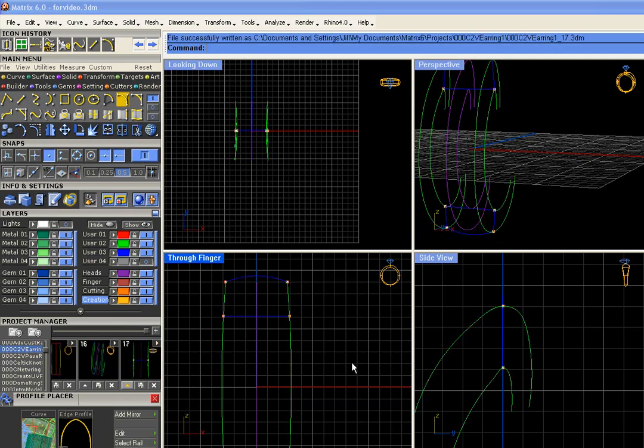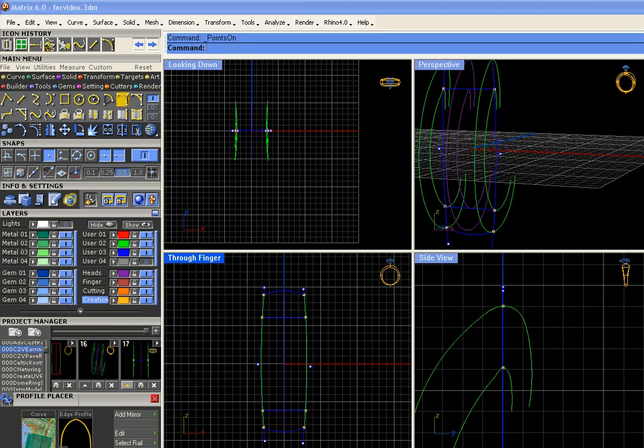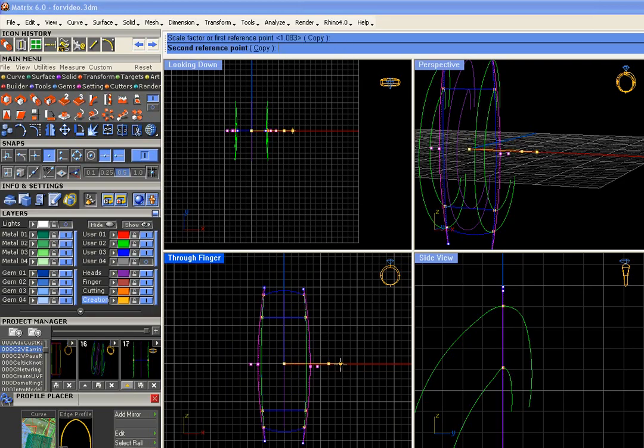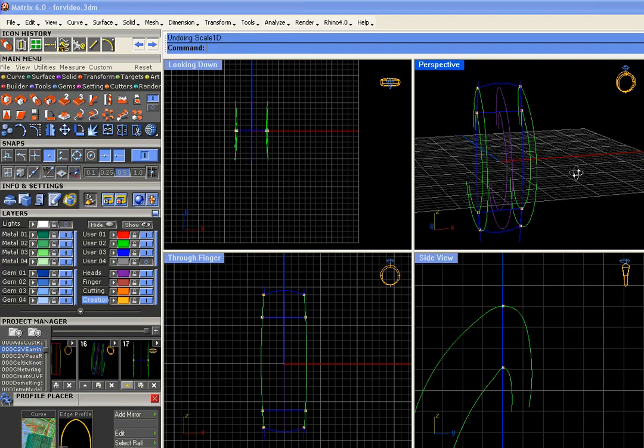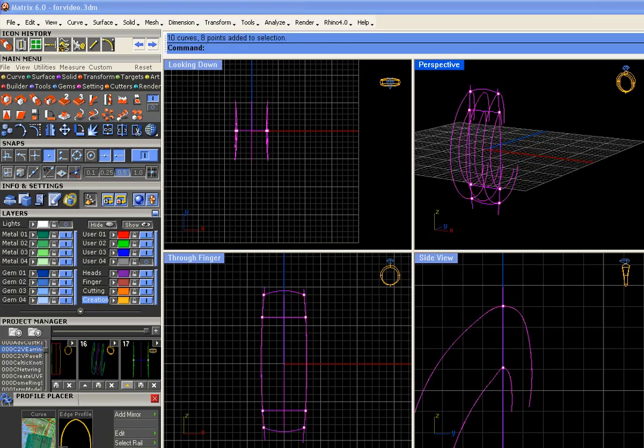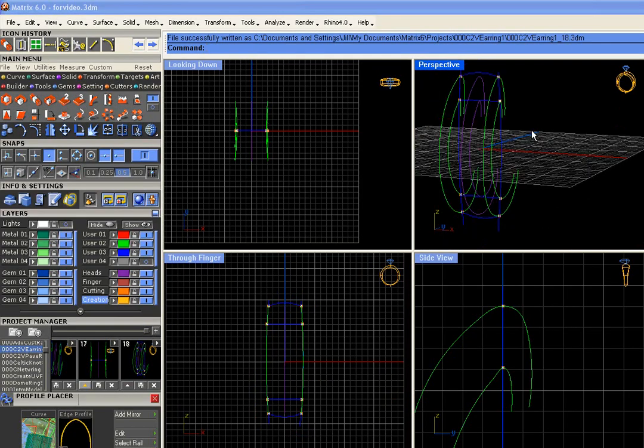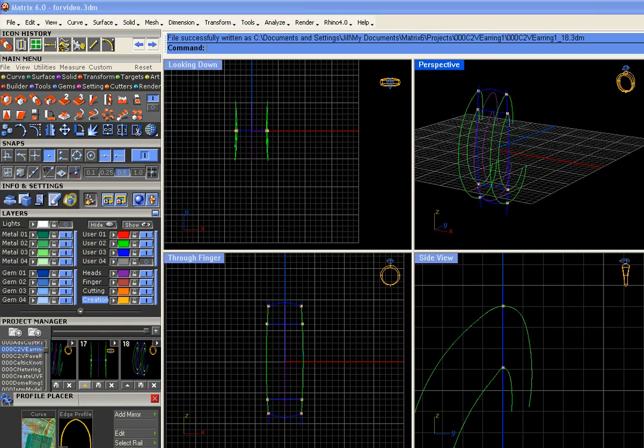And if you want to check and see, just bring back your original curves that you had hid, turn on their control points, grab them, and using, say, transform, we can push the center two outward. We should see the whole model change, and it does. Okay, so those still have history enabled. That's always a good thing to check. This tutorial is kind of to follow some a little more advanced uses of history. Okay, so that's how to check.